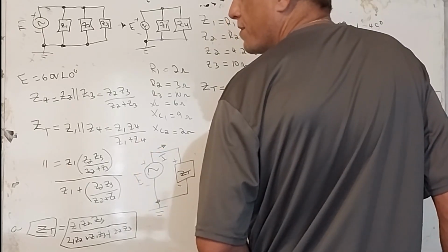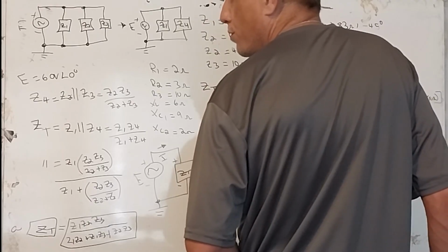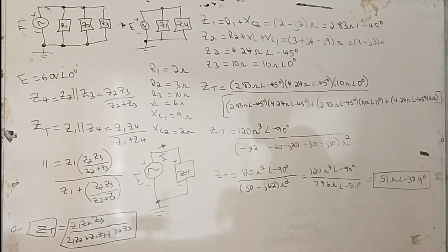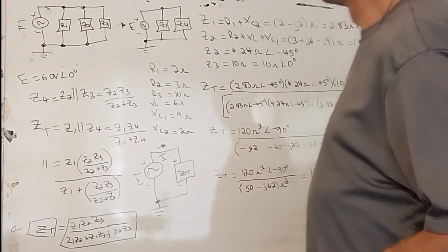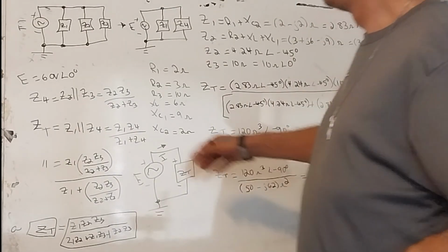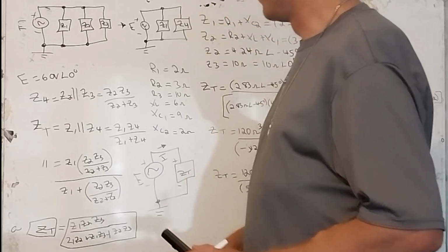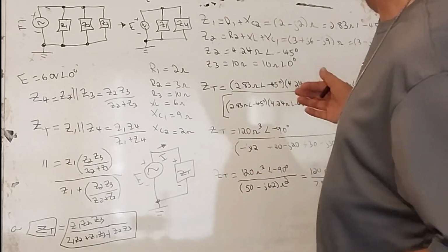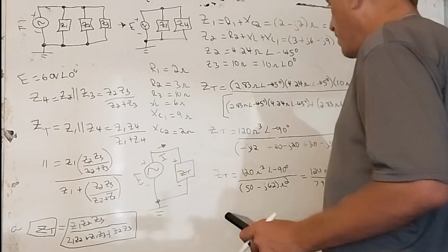Next, well, the second one's find the voltage V1 across the 2 ohm resistor using the voltage divider formula. The 2 ohm resistor is R1. R1 is the voltage across Z1. Even though these are all in parallel and they share the same source voltage, the voltage divider formula only needs to be applied with R1 and X of C2.